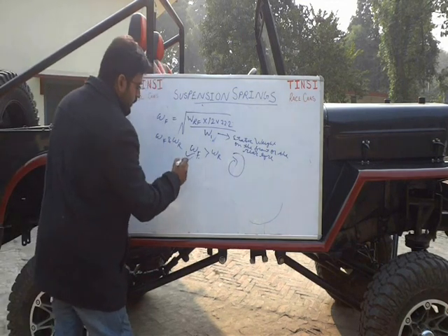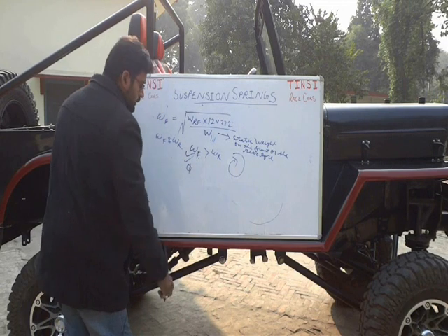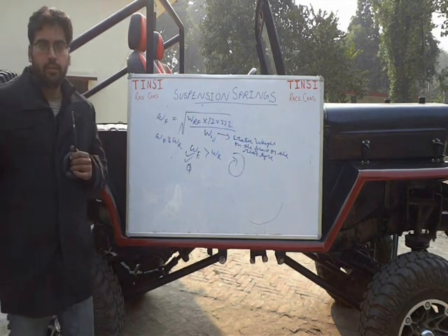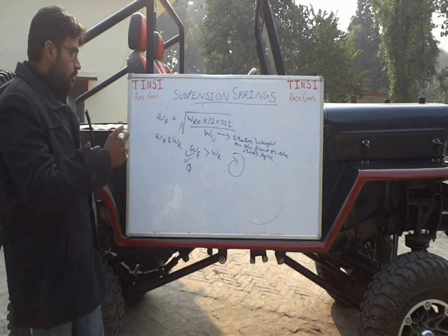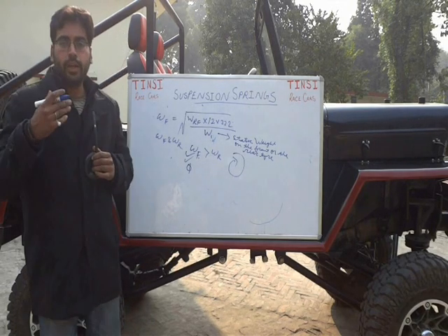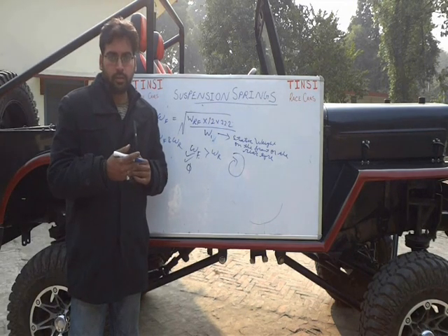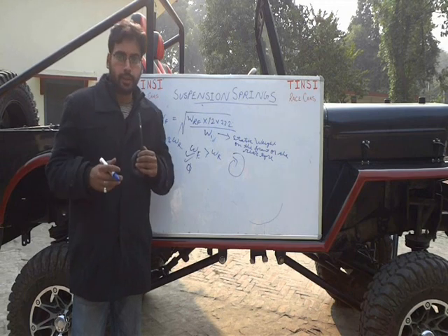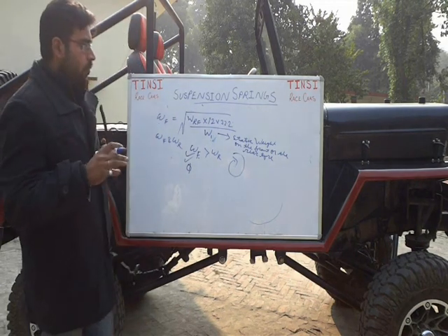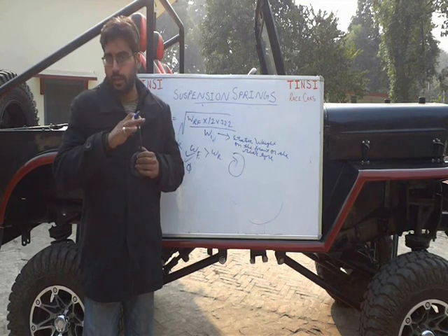Now assuming that you have got this, front is more than the rear, we go into taking out the roll gradient, with whatever roll rates we have assumed at this point. So for a particular g, like 1g, what is the amount of roll that we are experiencing? We don't want much roll because the steering response is suddenly gone.